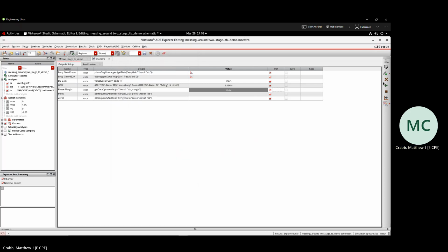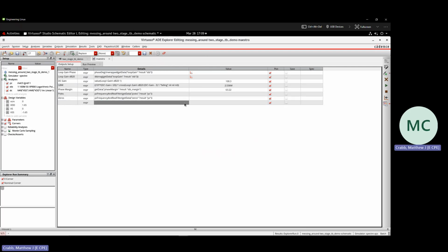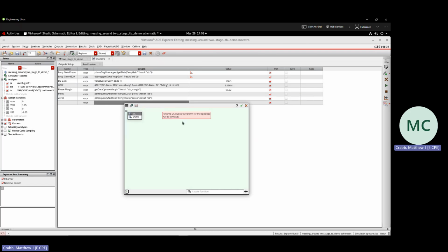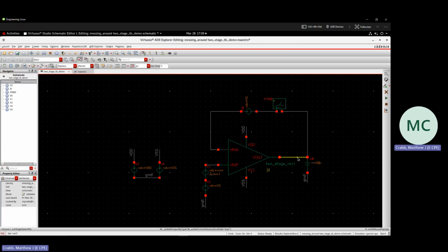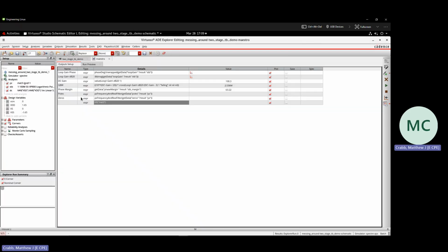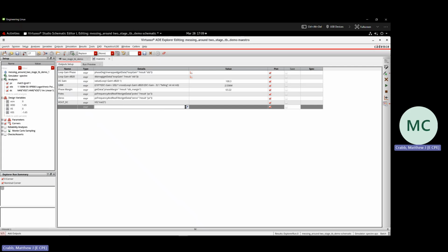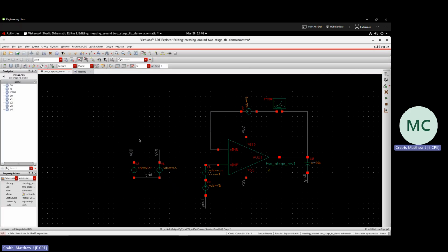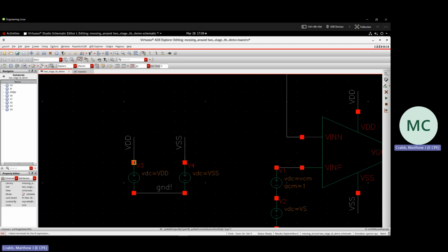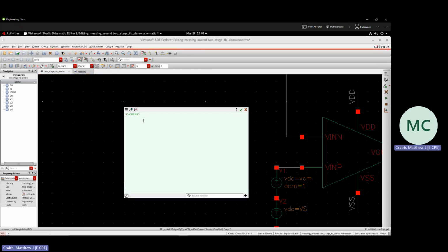And then I'm going to add a thing to plot here. So I'm going to add an equation. I do VS, which is a DC voltage sweep. And then I'm going to do this output node here. Okay. And then I'll call this Vout DC. And then the next thing I want to do is I'll add another one, and I'll do IS, which is for current, select from design. And I want to grab the current from VDD here. And then, so this is going to be the current from the supply, and then I'm going to multiply it